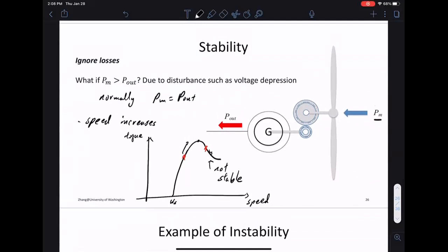We'll stop here today, but next class we'll pick up by looking at the stability issues, the idea of where I can dump power. I have more power from wind than I can supply to the load. That does not mean inefficiency. Normally we don't worry all that much. We worry about efficiency, but the loss of efficiency is not catastrophic. Instability is catastrophic failure. So we need to dump the power somewhere. So the suggestion of turning extra power into heat is actually a good one.